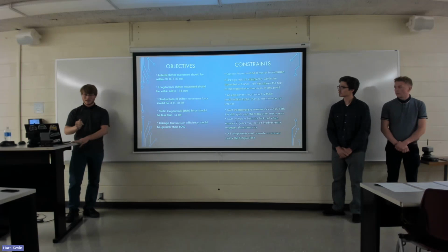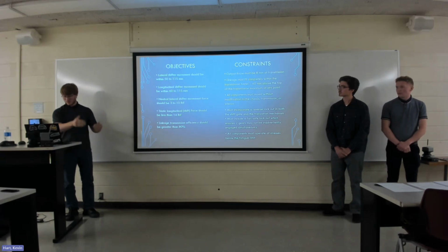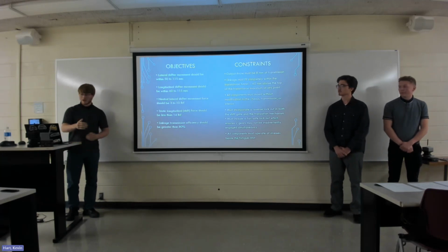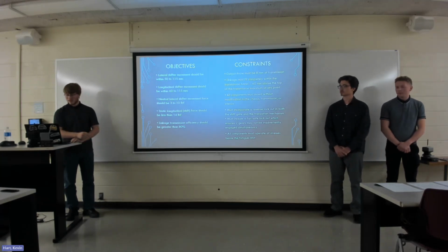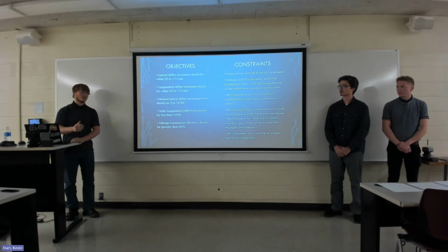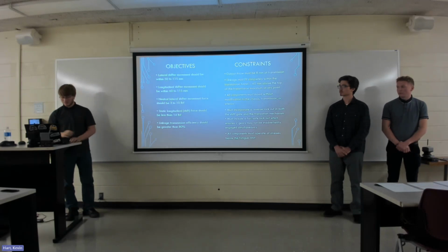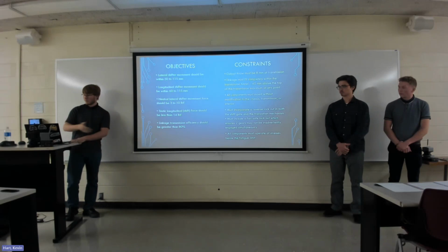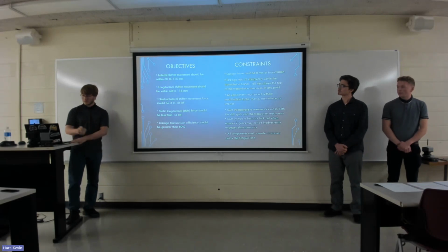So if we're engaged in first gear and you shifted to second gear, this would be that distance. Again, we found some cars which were very short at around 60 millimeters, and the longest acceptable range for us would be about 115 millimeters.